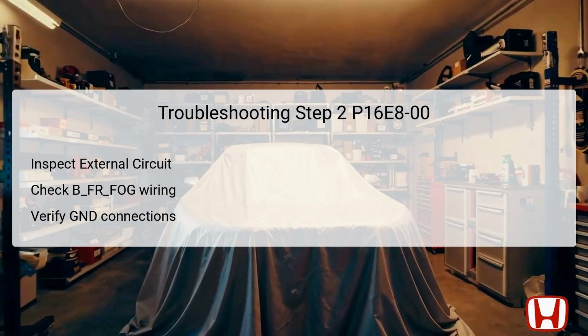The GND or ground connection must also be inspected, as poor grounding can lead to communication failures between components. Open or shorted wires can cause significant issues within the LIN, leading to the DTC being triggered. Attention to detail is crucial during this inspection, as resolving wiring issues can often rectify the DTC without needing further components. This preliminary work can prevent unnecessary component replacement and save time in the repair process.